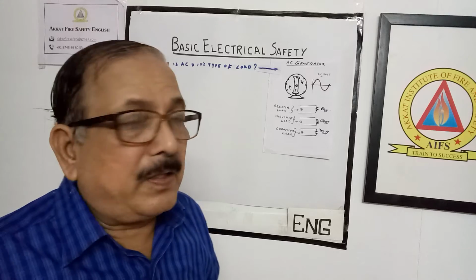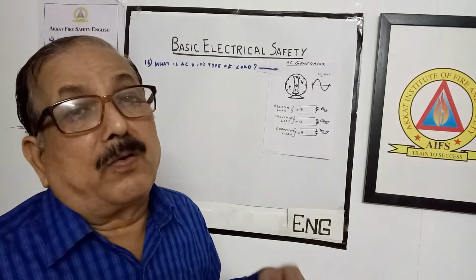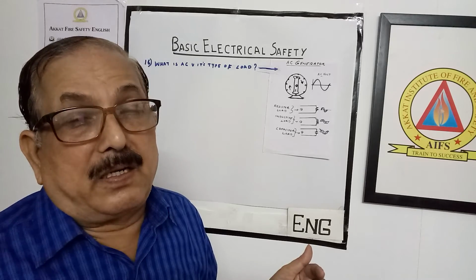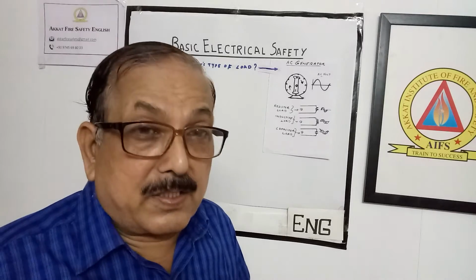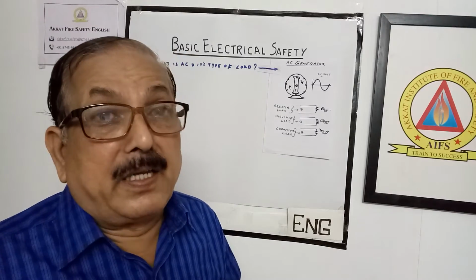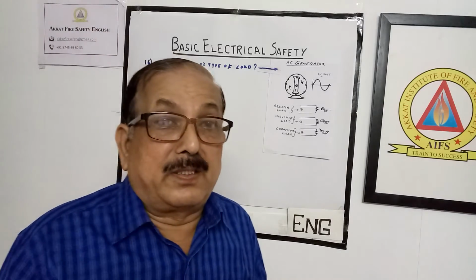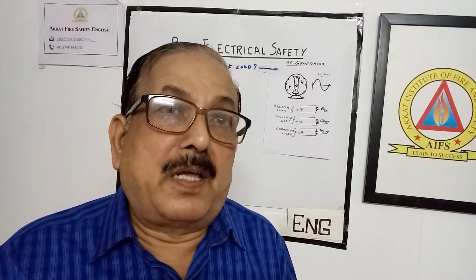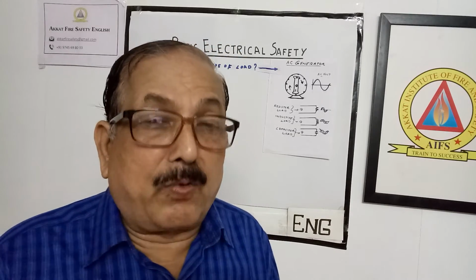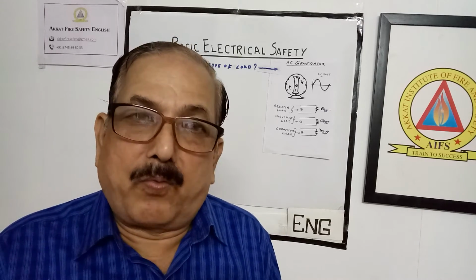So now what we understood is, in case of inductive load, current is always lagging. Sorry, in the case of inductive load, current always lagging. In case of capacitive load, current always leading. That's why we are using capacitors in many AC lines for power factor improvement, because what we require is the power factor should be 1 only.